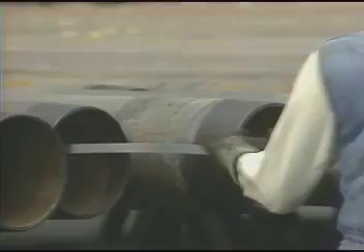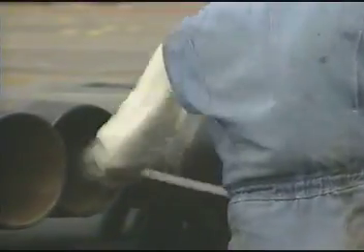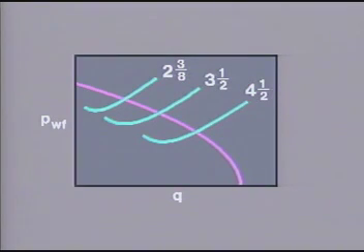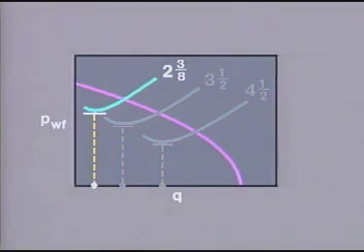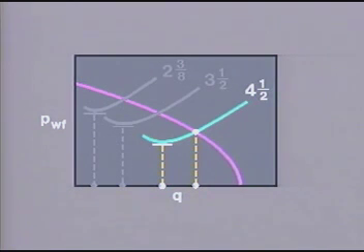Of course, the tubing size we may choose for our completion will be constrained by the size of the production casing. But simply choosing the largest possible tubing in order to maximize the initial rate is not a prudent design. For any tubing size, there is a minimum flow rate that is required for continuous removal of liquids. Below this rate, the well will be unstable as slippage of the gas phase through the liquid results in liquid holdup. The larger the tubing diameter we choose, the higher will be the rate at which instability occurs. So by choosing a large diameter tubing string, we may be sacrificing long-term producibility for short-term productivity.